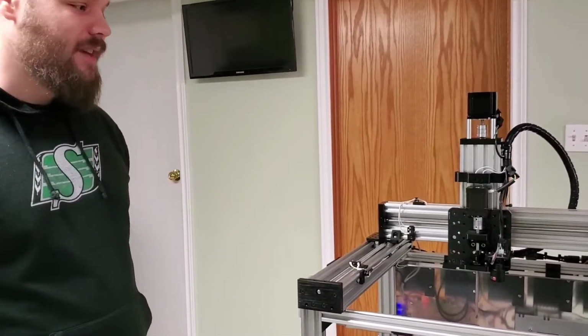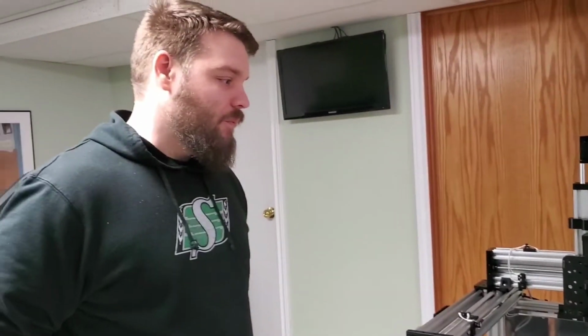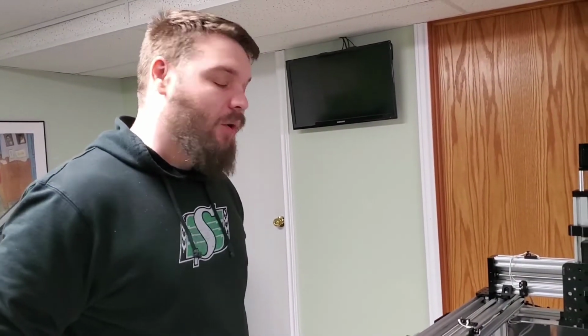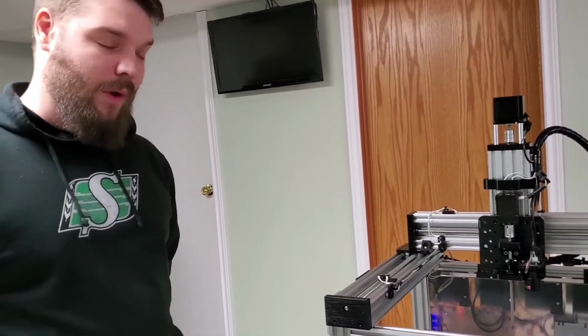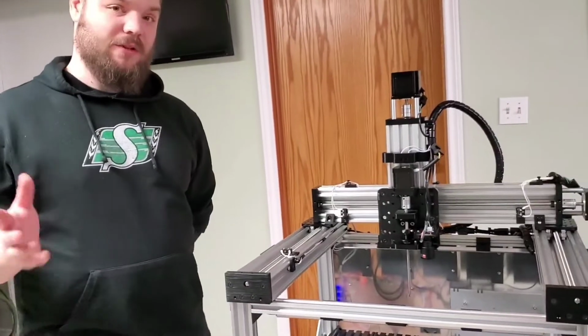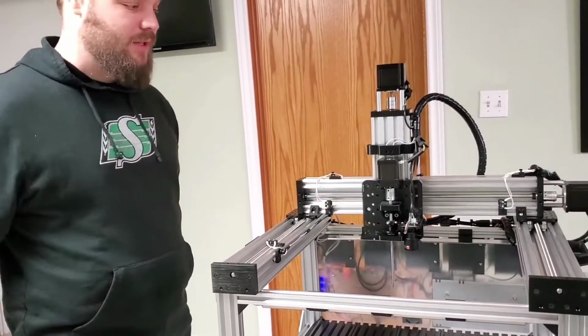At 1/16 microstepping, we're able to rotate as small as 0.1125 of a degree. With our error, we have 0.25% error for each degree. So if we're to turn a degree, it's only going to be off by as low as 0.25%, which is quite good. We were aiming for at least 1% error, which we've achieved in this particular system.